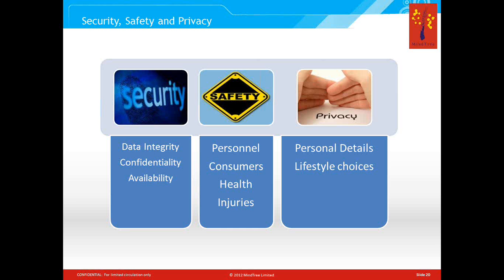So what may happen? If you want to take corrective action, depending on the situation, the only option left will be to go door to door and change the firmware, because the malware which is installed in the smart meter may not allow any more firmware upgrade. So the only way to change the firmware will be to visit and change it. That is a massive headache for the utilities, and this can happen. The researchers have demonstrated that such things are feasible.